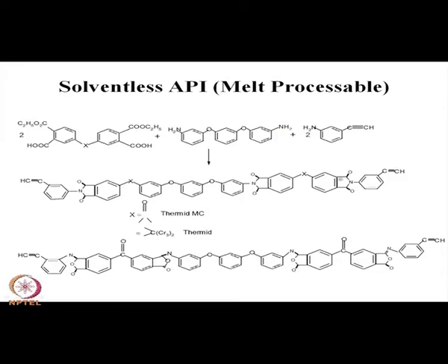So, inside the molecule there can be imide linkage, there can be ether linkage, there are phenyl rings. So, that contributes to the rigidity, thermal stability, flexibility, toughness, all those will be tailored by the presence of such groups and moieties, whereas at the end there are acetylene groups present, which will help in curing of the resin.